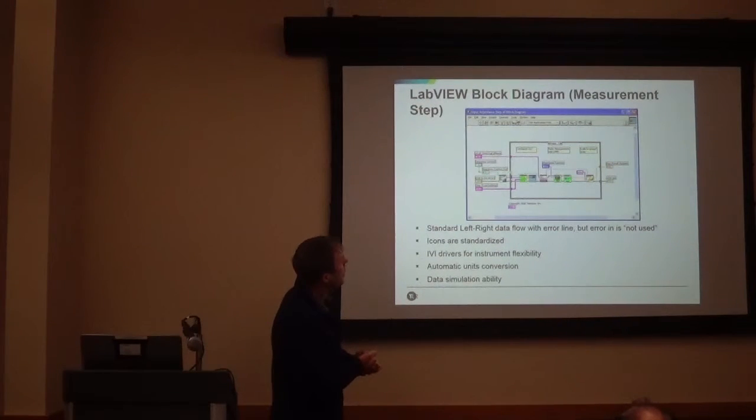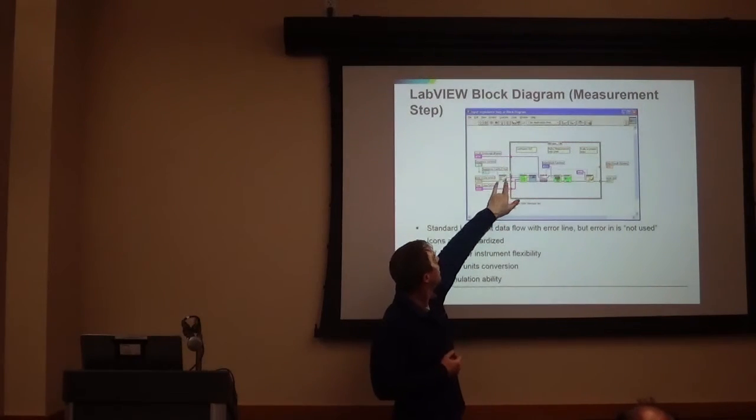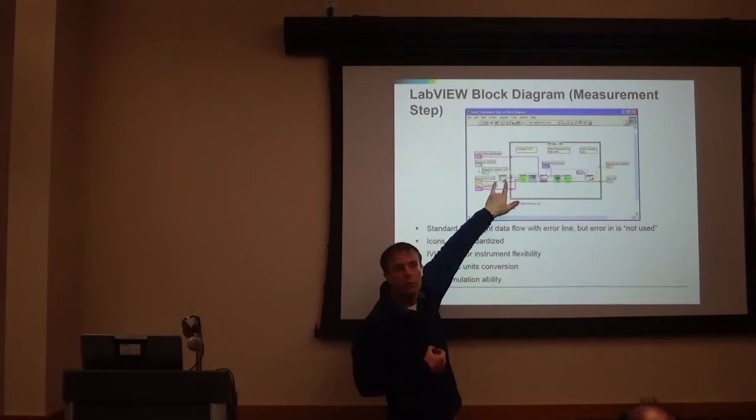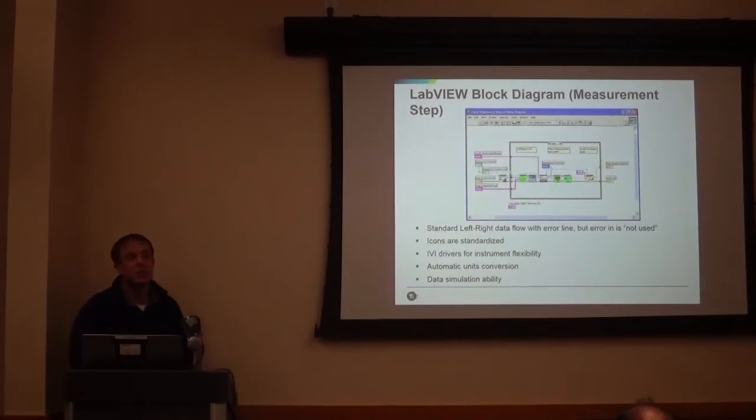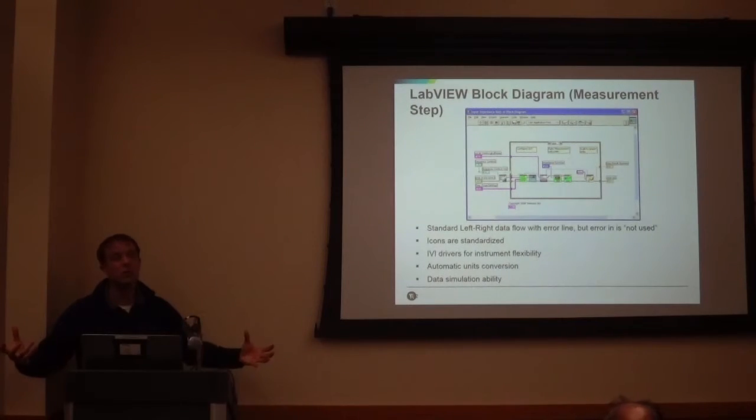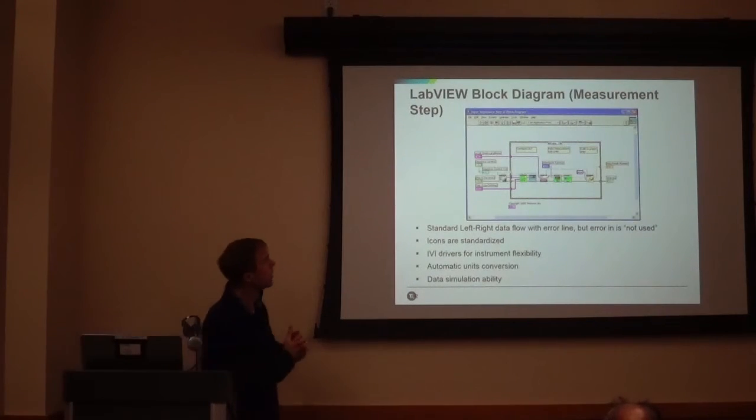Internally, things got swizzled around a little bit. Pretty much the majority of our tests start off with an environment VI that goes back to TestStand and understands what's the environment that we're running in, and handles a lot of it for what is the UUT, how are you talking to the UUT, whether you're in a simulation mode or not. We can swizzle some station globals on the station and put it into simulate mode where we can fake talking to the instruments and test the general sequence execution process without actually having to communicate to any of the hardware.